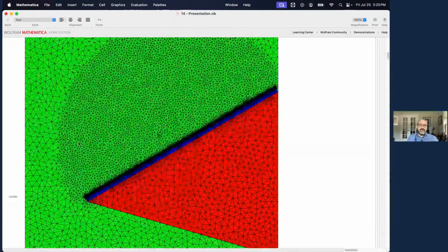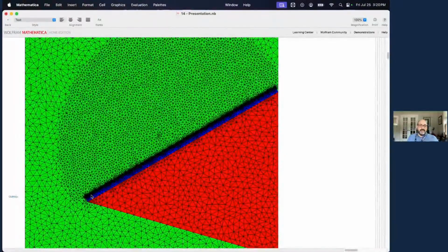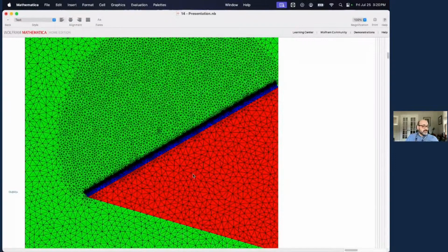In the meshing here, you have the air area interface, you have your condenser, and then you have your actual condensation surface. What is this red below? This is actually an optimization technique. When you have air flowing from the left to the right, you don't care about this area. This is an insulator, so the heat transfer in here is not going to be important.